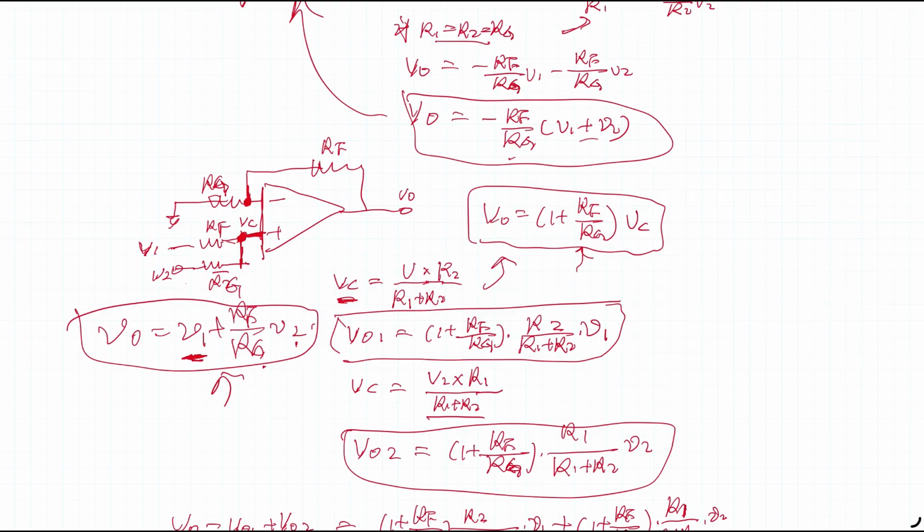If this is V1, basically you can easily use this topology to add an offset to a signal. For example, if your V2 has a sine wave input like this, and you have a single power supply rail, your output will be limited to the positive cycles. In this case, what you can do is set V1 equal to half the VCC. Okay, then you can shift this whole curve up to the middle of the power rail. Then you can display both sides of the AC input.